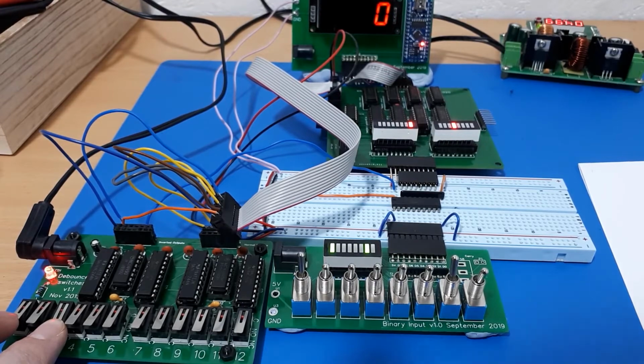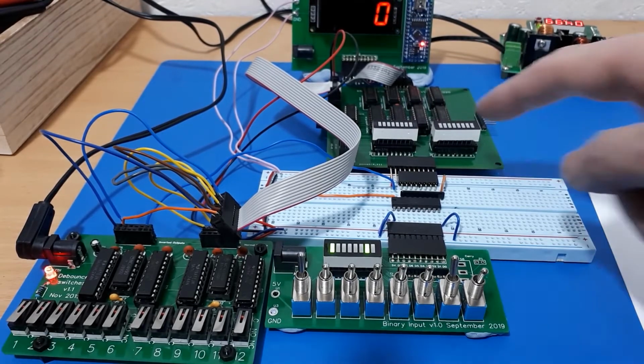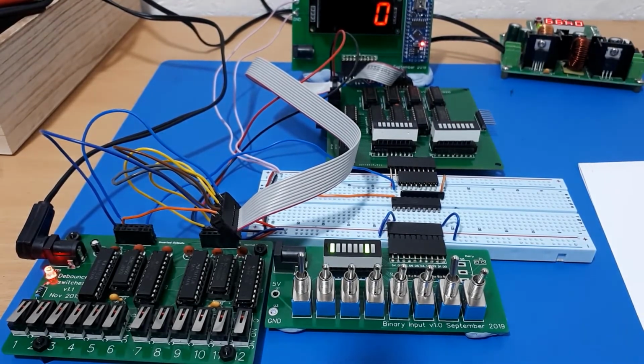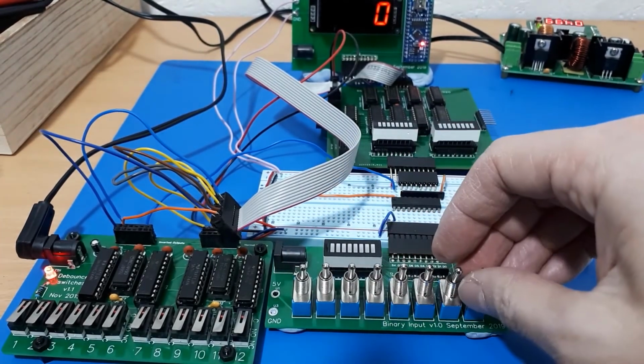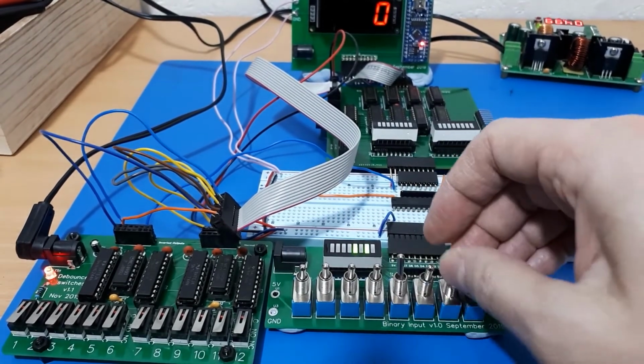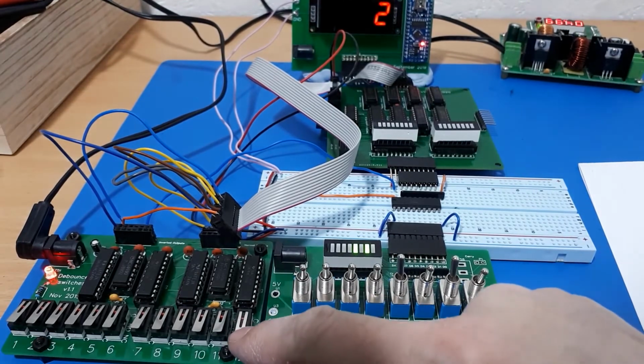Let's do the reset. So to do a reset, you hold down 2 and do a press on the clock. It's a synchronous reset as well, and it's gone to 0. Right, so what happens if we want to put a value into the program counter then? Well, if we put a value on the keyboard here, so let's put 10 on there. Let's check, publish that.